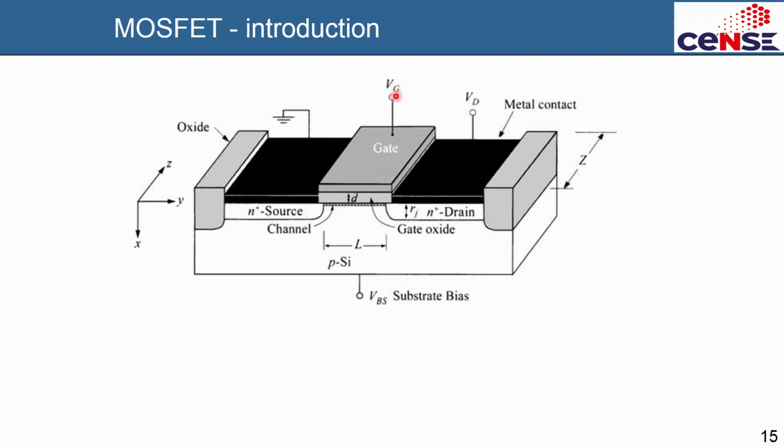So that means because of the field, there is a plus 5 volt or maybe plus 3 volt, there is a 0 volt. So there is a field between source and drain that will lead to a drift equation, or the transport of these electrons that will try to flow from the source. This is like an infinite reservoir of electrons, because you are already connecting it to the ground, you are completing the circuit. Your electrons will try to flow so that you will get a current across this channel here. Electrons will come out from here, which means current actually is going in here. Okay, that's the convention.